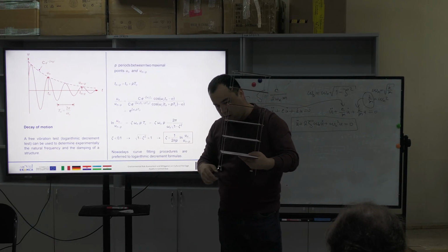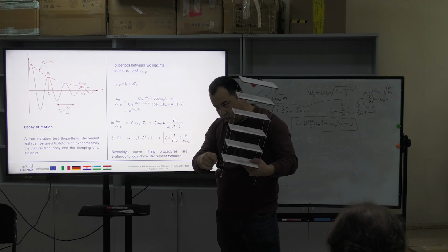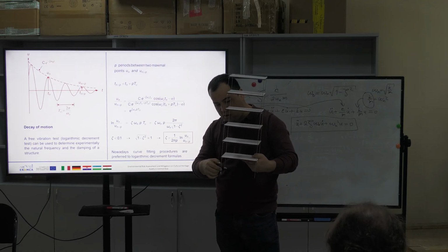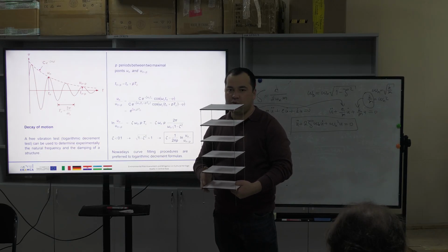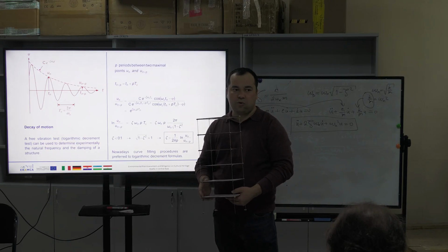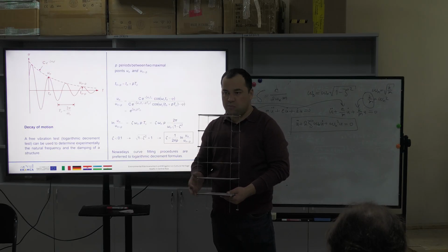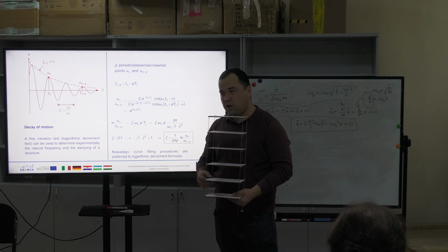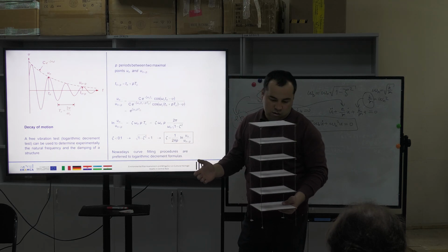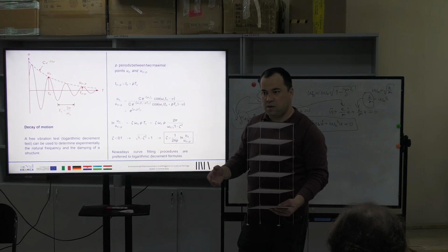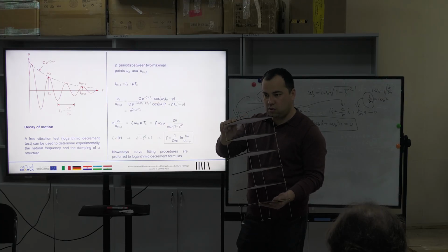You have to compare the horizontal and vertical motions to each other in order to identify the natural frequency of the building. If you have a less accurate sensor, you can still measure the building's natural frequency. Of course, if you have a higher cost, more expensive sensor, you can also measure the building natural frequency easily. Okay.